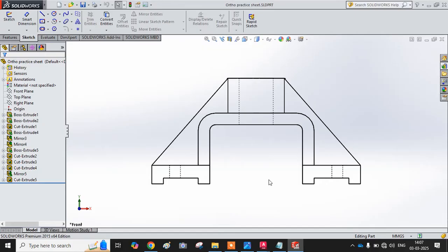That is why to draw any 3D object from 2D, we require at least two views. With the help of one view, we cannot draw the 3D object. So in orthographic projections, if you have been given two views, you can retrace and redraw the 3D dimension. That will be a difficult part. We will call this isometric. 2D is given, 3D has to be drawn; we will see this last. It will be slightly difficult. A lot of imagination is needed to make 3D from 2D. Okay, right now 3D to 2D is going on. Okay, is it clear? Did you understand?